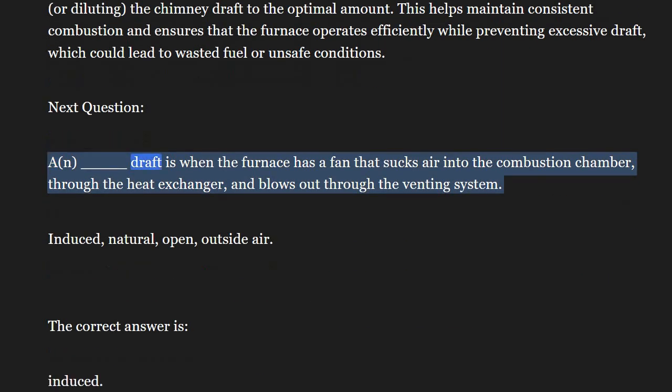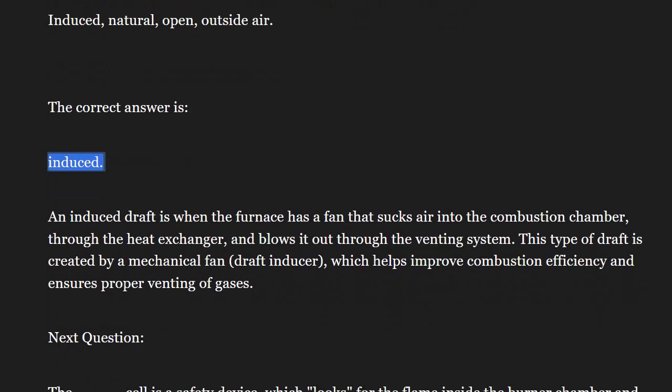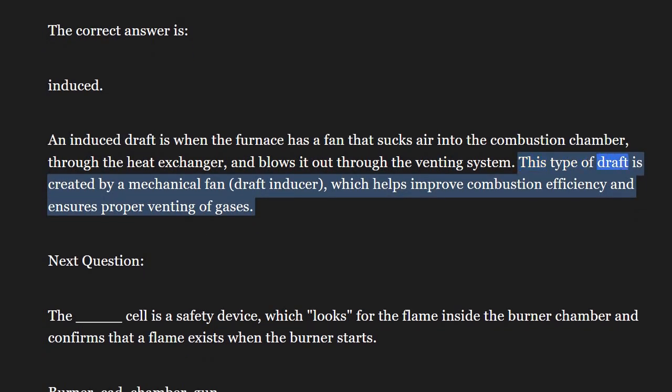Next question. A ___ draft is when the furnace has a fan that sucks air into the combustion chamber, through the heat exchanger, and blows out through the venting system. Induced, natural, open, outside air. The correct answer is induced. An induced draft is when the furnace has a fan that sucks air into the combustion chamber, through the heat exchanger, and blows it out through the venting system. This type of draft is created by a mechanical fan, which helps improve combustion efficiency and ensures proper venting of gases.